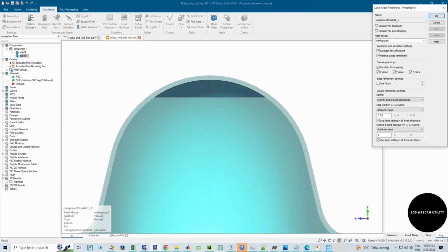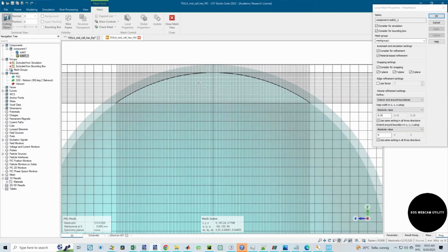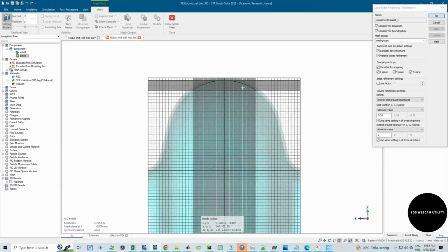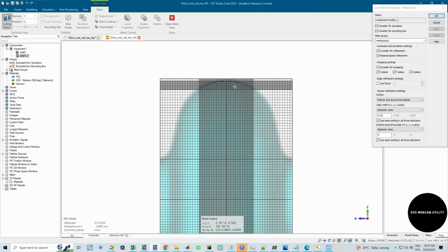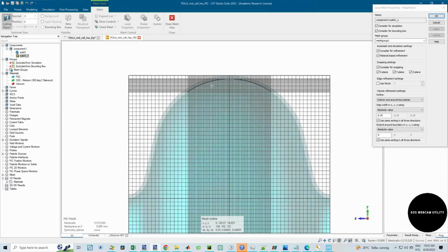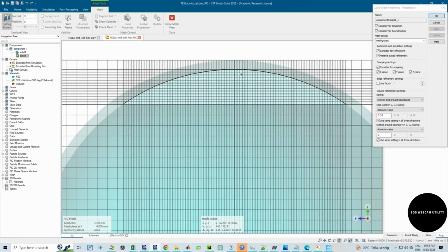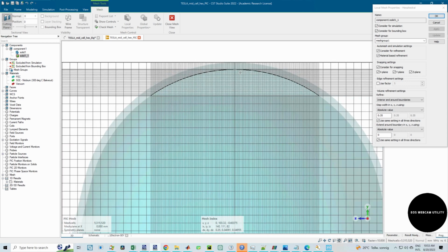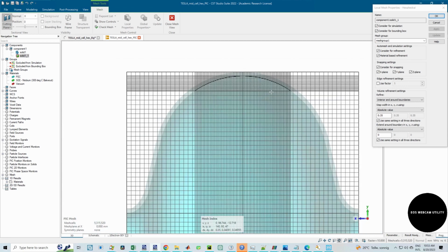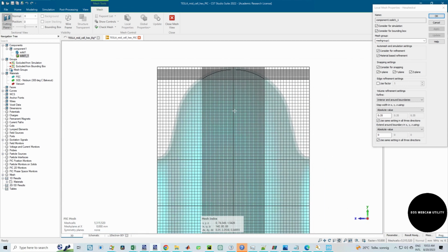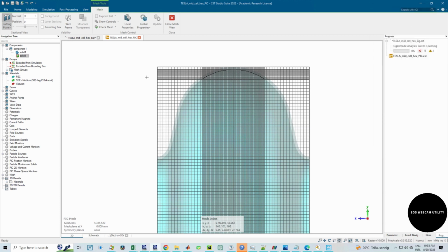Let's see how coarse this is. I think this is okay. It's manageable. Just a note, if you run the multiplexing simulation and you are sure that multiplexing should occur at a particular fit value and it doesn't occur, then you should look at your mesh. You should make sure you refine your mesh very well, just to eliminate that from the list of possible causes. I think it's not very fine, but let's see. I hope it works.